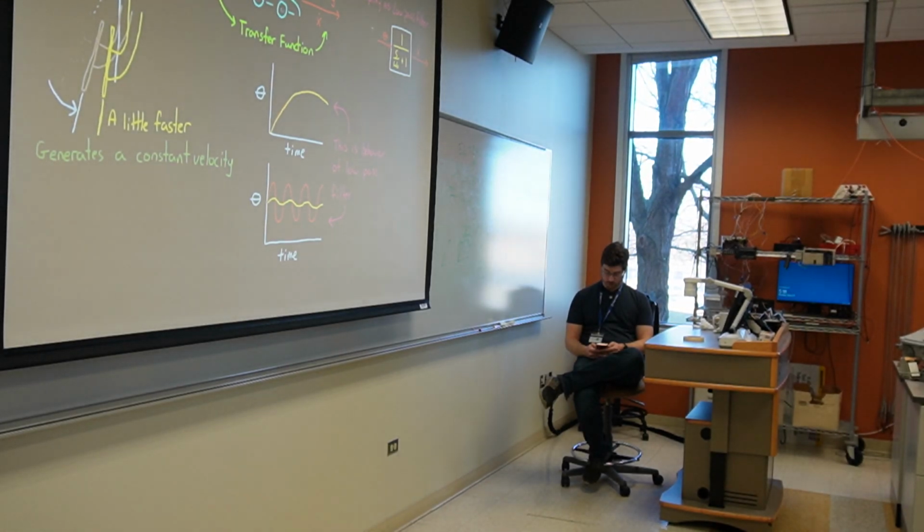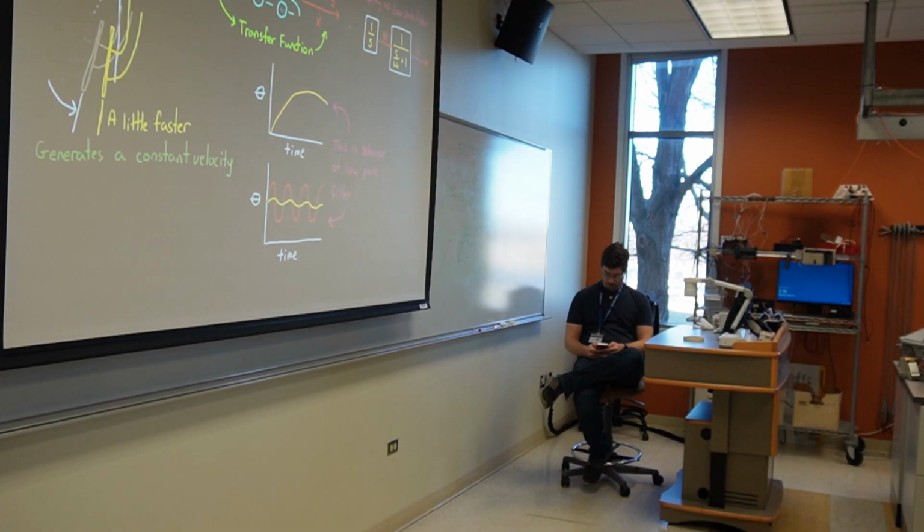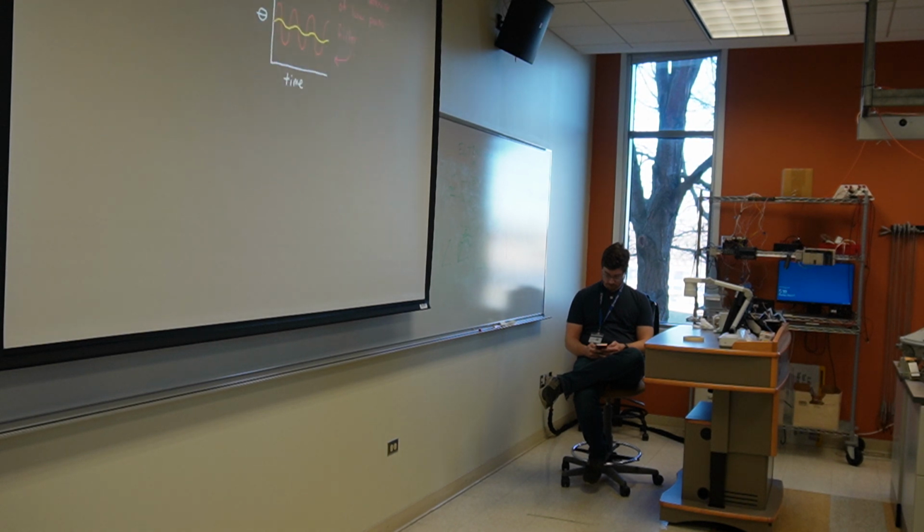So our command is actually a change in angle over time, which can then be integrated to produce an angle, which is the input into our low-pass filter. So the transfer function from the change in the gas pedal angle to the velocity of the car is then combined and would look something like this. So keep this model in mind as we go through the exercises.